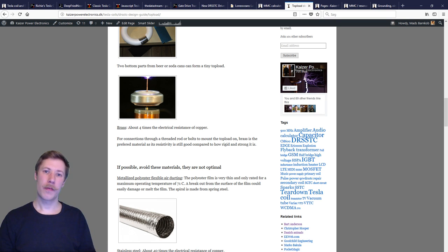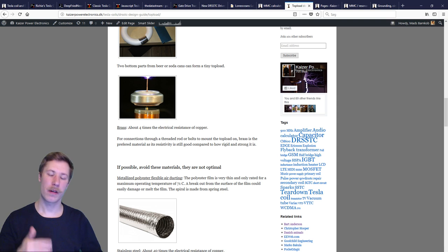or the amount of power needed for the Tesla coil to build up enough charge on a very smooth surface toroid can simply be too high a load on your inverter, and you can simply risk destroying your inverter if it has no breakout point, simply because it will have to push such a huge amount of power into the secondary circuit before it will break out. So you have a huge circulating current that will go back and forth, and it will simply run into a self-destructive mode. Or you will have huge sparks lashing out here and there that you have no control over. So that can quickly get a little scary.